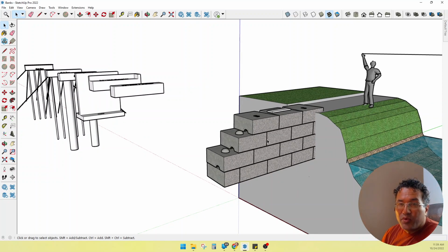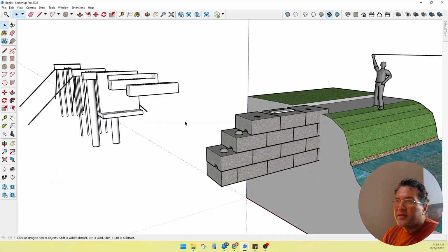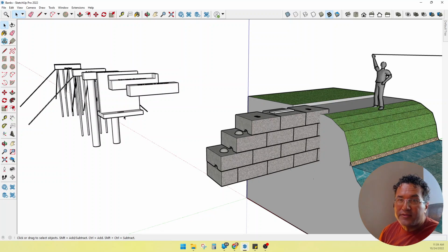If you have poorer soils, you want to go deeper, and that's going to be true for all of these. The reason they get deeper is because you have poor soils. If you have great soils, then you can get away with a much smaller abutment. But if you have to dig down further to get to good sound soils, then you have to go deeper, and that's where we start using these other ones that are much deeper. And the cost starts going way up, right? But this is the least expensive. Let me pull up a few pictures of the precast option.